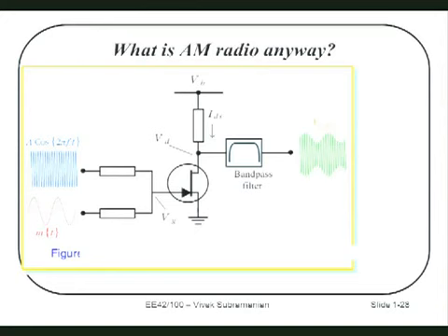So you've heard of AM and FM radio. What does AM mean? Amplitude modulated, and FM is frequency modulated. What does that mean? Here's what we do. In an AM system, we have a carrier wave that is oscillating at a particular frequency. For example, the traffic station that most of us in the Bay Area listen to is 740 AM. That's at 740 kilohertz.